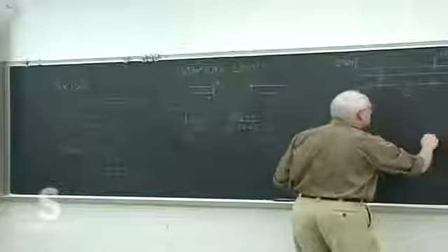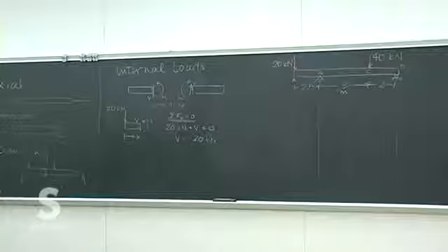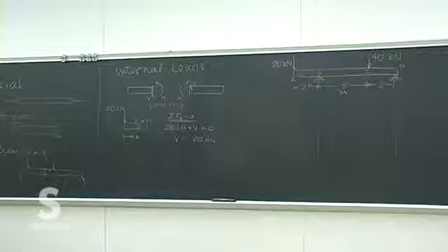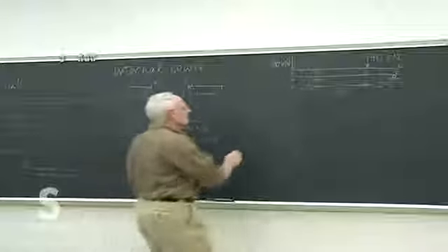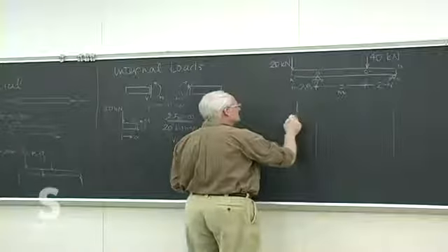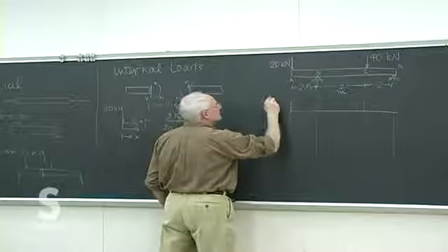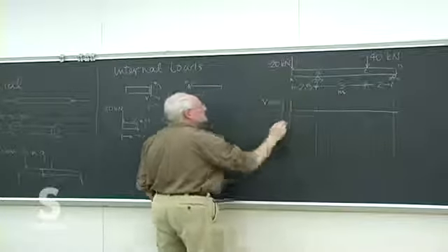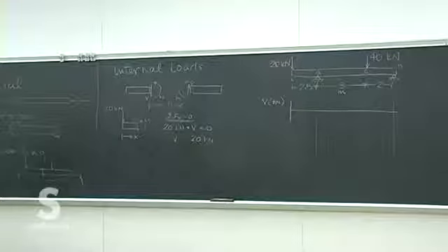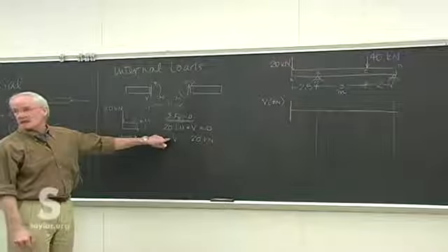Again, my recommendation is that you draw these above and below each other as we go through these, so that everything just makes sense. You can use certain places to double check. So we'll graph the shear as a function of X as we go. And we already know between A and B, we don't have to do anything else because none of the load changes in that region. But from A to B, we know that the shear is minus 20.